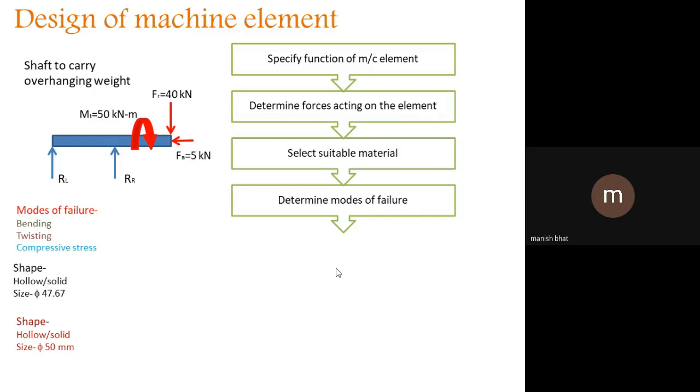When the fan is continuously rotated, if it is not correctly fitted to the ceiling, it wobbles. Due to that wobbling action, bearings will fail and that noise can be heard. So we say we have to change the fan, meaning the fan has failed due to bending.